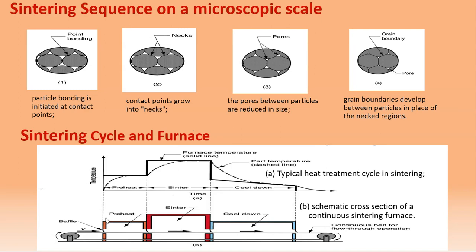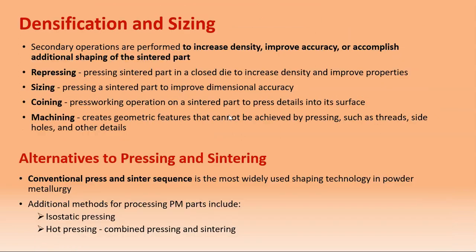And we can see that this is the furnace for sintering. It starts from here, so they have to increase the temperature in stages. So we can see here they have the preheat, and then this is the sintering temperature. Usually they have the highest temperature before the melting point, and then they have the proper time, and also they have to go through the cooling part. Okay, so they have to have the proper cooling down time.